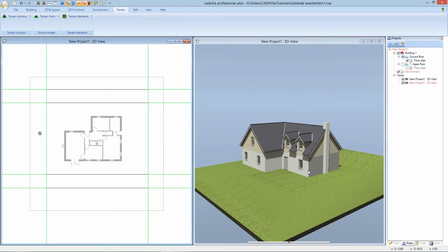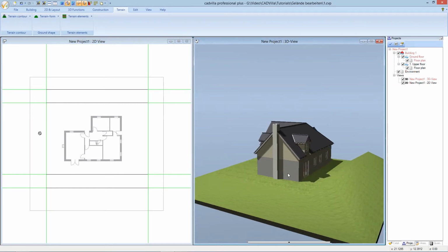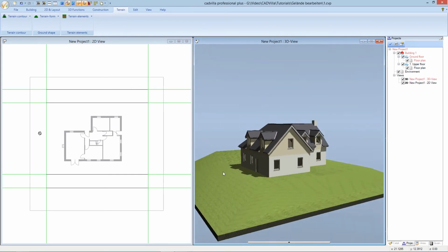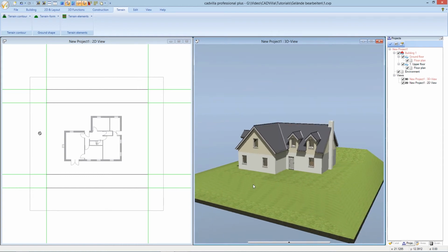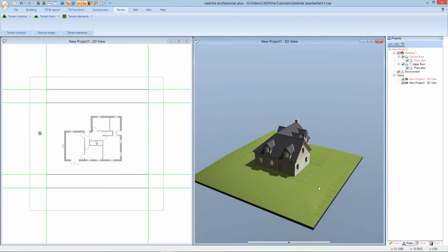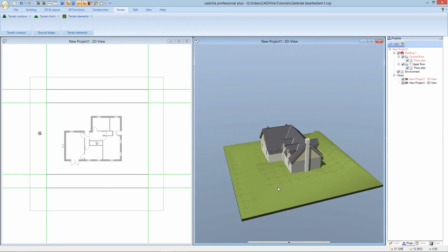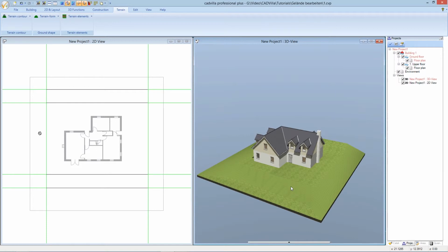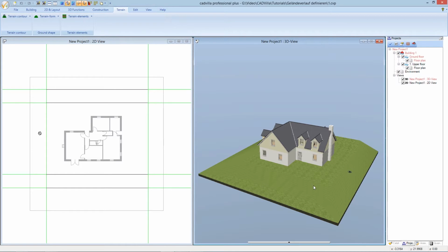and now we can take a first look at our finished defined terrain gradient in the 3D view. As you can see, we have 3 different levels with -2, 0 and +2 meters. Of course, this is just an example and you can edit the terrain in your project like you need it. If you like to define a ridge or an immersion inside the terrain surface, you should define the lateral height contours.